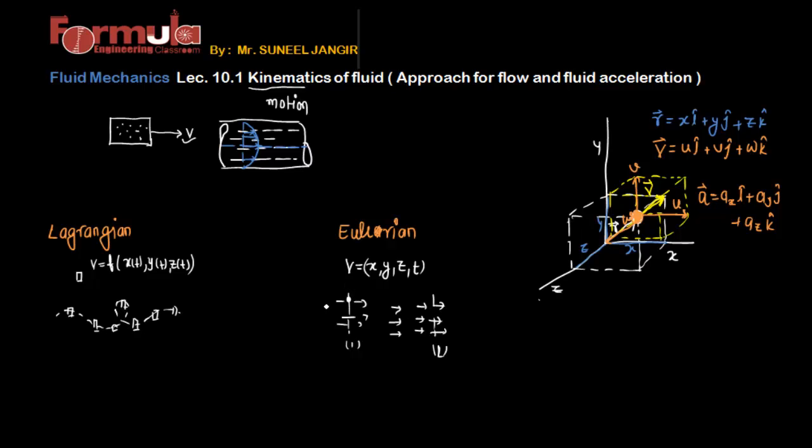It means we are at a point, and in this case the particles are coming in and going out from different points. So the Eulerian approach is the point approach and the Lagrangian approach is the particle approach. Now the answer from both approaches is the same. But the problem with the Lagrangian technique is that a single particle doesn't define the complete flow. That's why this approach is insignificant, and actually laborious. That's why we simply follow the Eulerian approach.